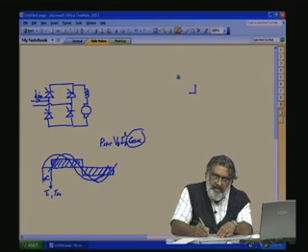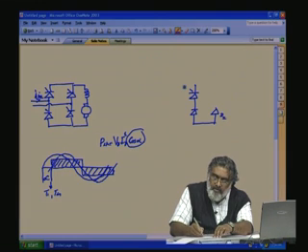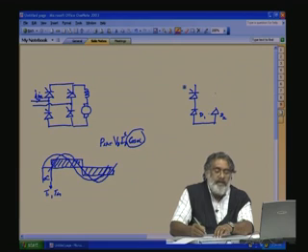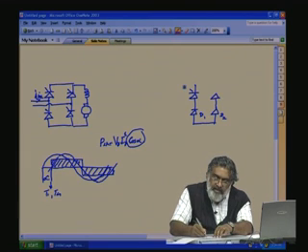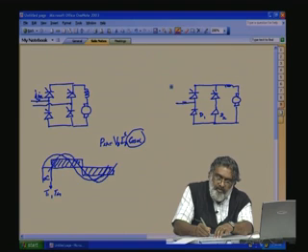In the last class, the single phase full wave semi controlled converter will be like this. This is the diode. We have 2 diodes, at the bottom portion we are using only diodes, this is D1 and this is D2, and at the top you will have the thyristors to control the output voltage. So, this is our load, which we can represent as a DC motor. Here this is the input current I1.